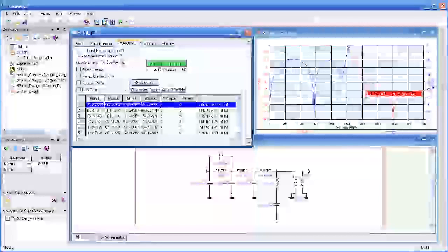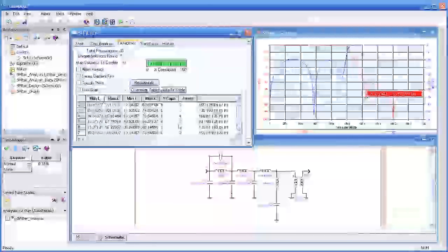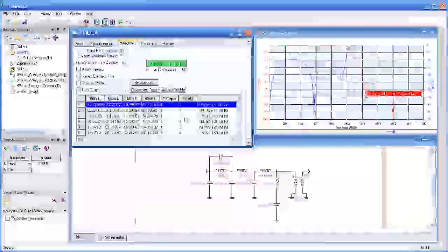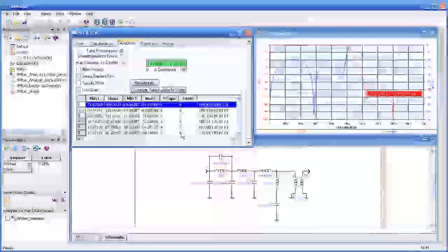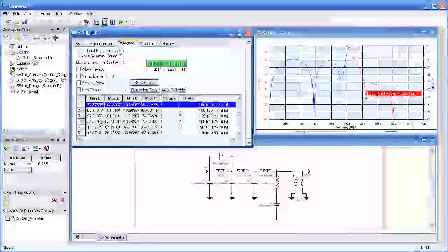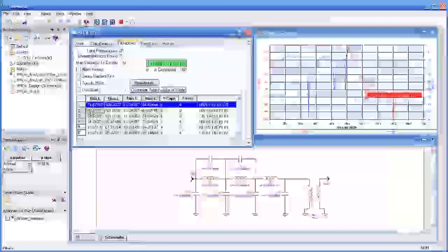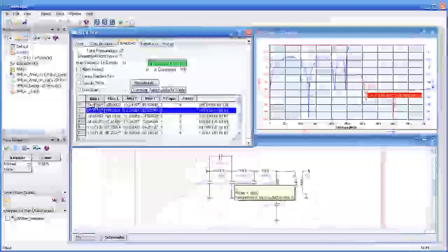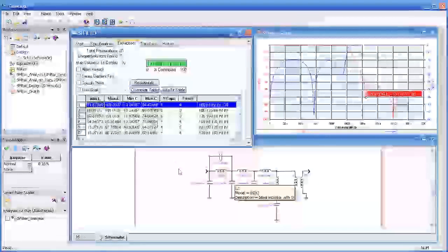What that means is that you have 20 different topologies that can be realized to express the same response. The difference is based on the number of caps and inductors and how they're placed in the circuit. So if we were to step through those, we could see it would be the same response for any of those permutations. It's just the topology changes slightly, and one might be better for your purposes than another.